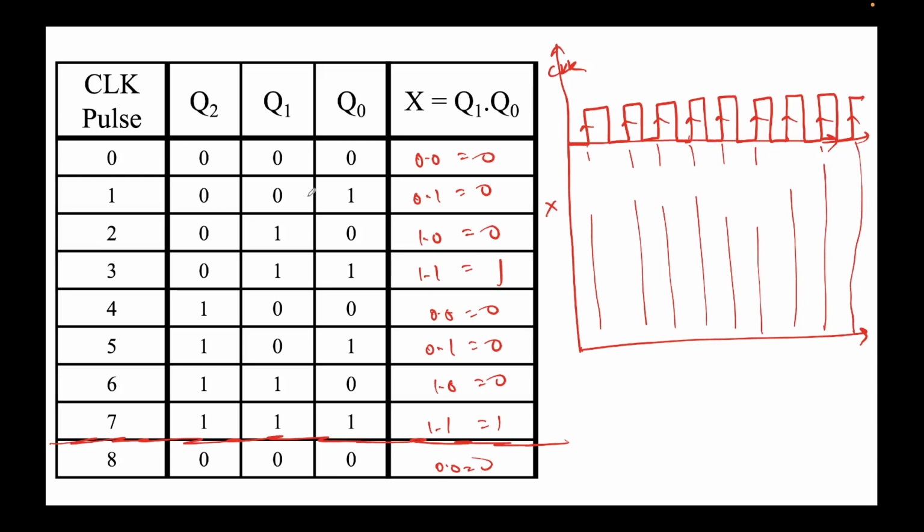All right. So the initial value is 0. At the first clock pulse, it's 0. Only at the third one it rises. So this is after the third one. So first, second, third. It will remain 0, and it will rise here. Okay, and then it will fall at the fourth, right? And then fifth, sixth, seventh it will rise again. It will fall. And then you can see that after 7, this is corresponding to 8. I told you this loops around to 0 0 0, right? 9, 10, 11. So this is third, this is 7th.